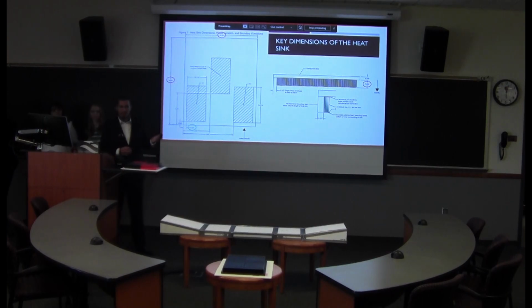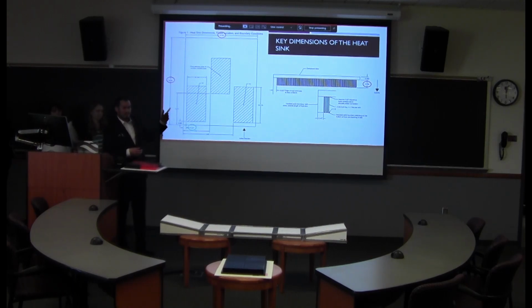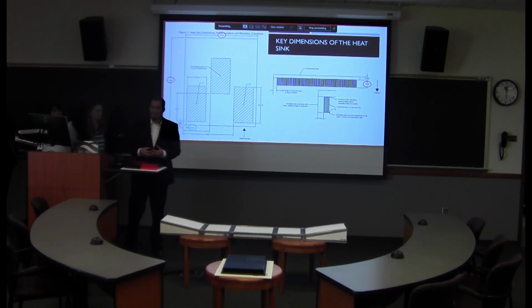Now here are schematics that BPMI has given us. There's 2 things I want to point out that will be valuable later in the presentation. First is the 3 shaded areas here. These are known as the hot spots. So the heatsink will be receiving heat at these 3 hot spots from the device it's connected to and dissipated through the fins. Another thing that's unique is that the heatsink itself is upside down. I would like to point this out because you're going to see some simulations where the heatsink itself is right side up. And since we're pushing air through, it's forced convection, so heat transfer and pressure drop do not really change if the heatsink's upside down or right side up.